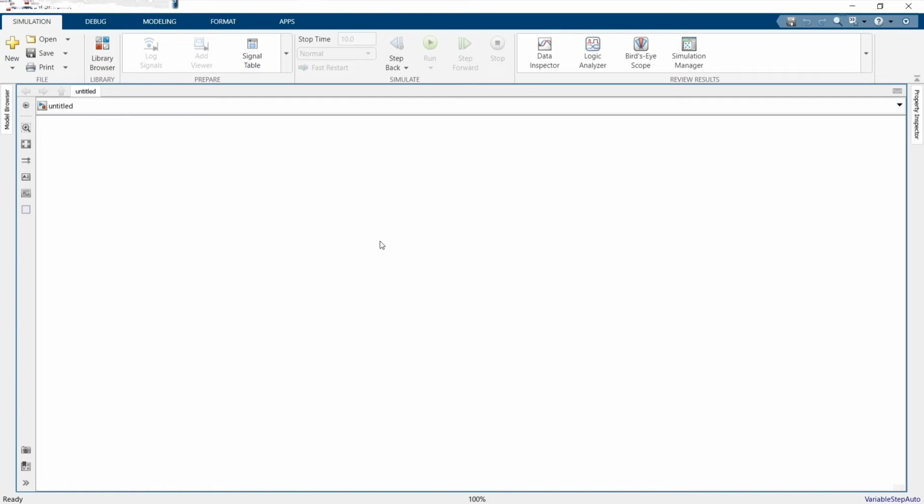Remember, this demonstration video is from a full course on hybrid electric vehicle design, modeling in MATLAB, and product design using MATLAB. Hence, these duty cycles are already discussed in previous chapters. So for generating a duty cycle, we need a V bat, then we need a gain to normalize the V bat. Normalize means I'll divide this by 58.4. What is 58.4? This is the maximum potential of the battery when fully charged.